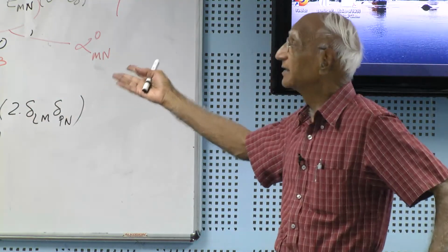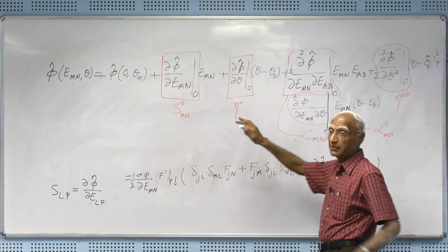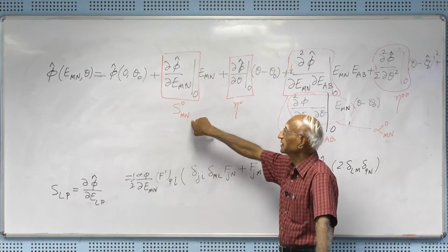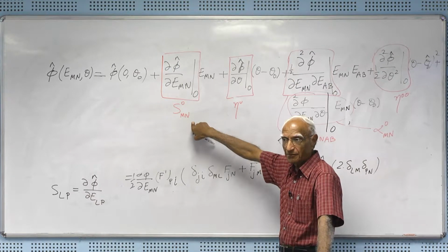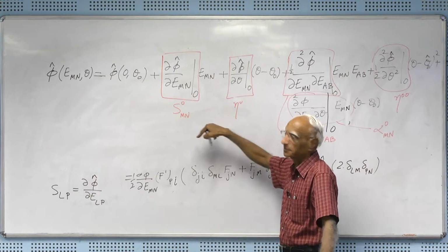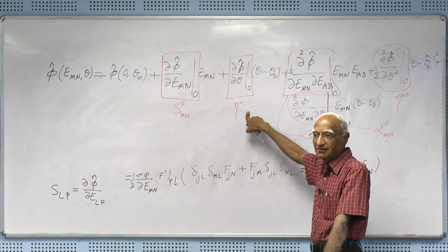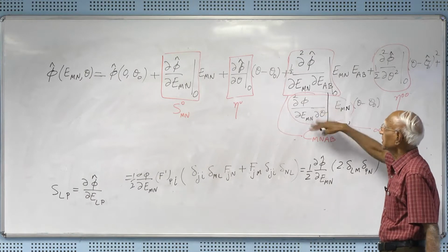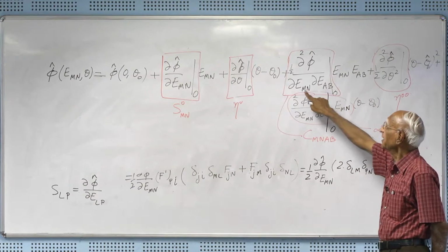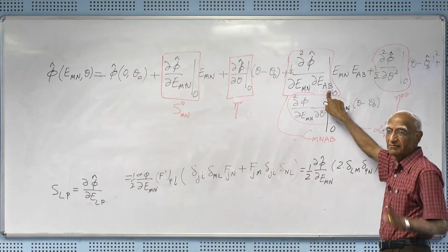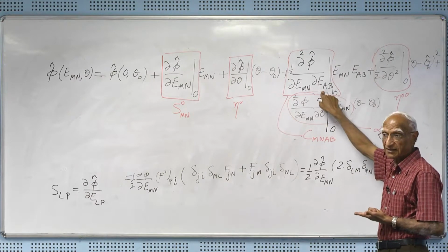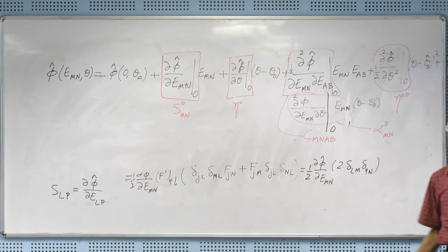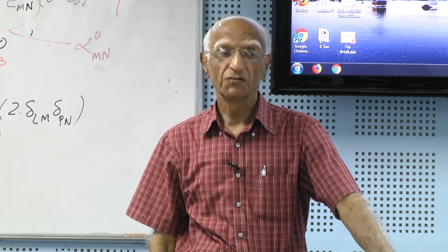Even in this case, you will see that finding variables is not that easy. The physical meaning of this is going to be the stress in the reference configuration. That's why I put 0 on top. This is the entropy in the reference configuration. This is thermal expansion. So this one, MNAB, these are 6, these are 6. So you have 36, but these can commute. So you really have only 21. So these are 21 constants.